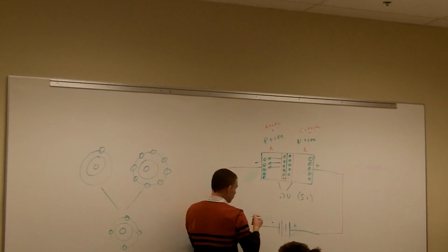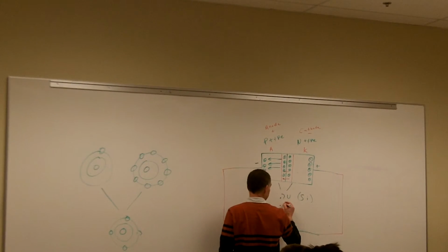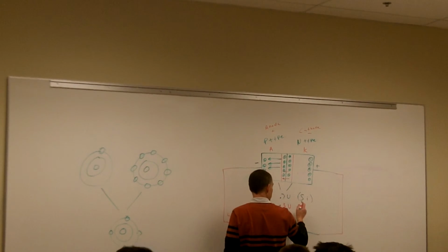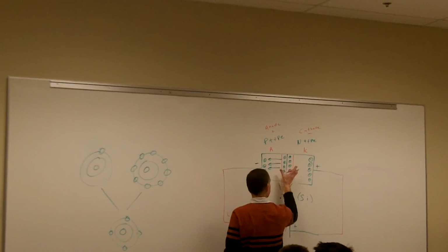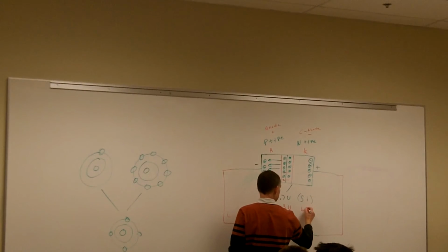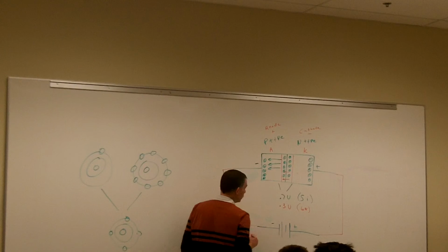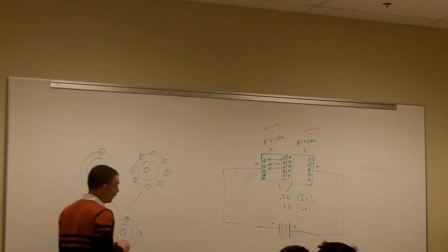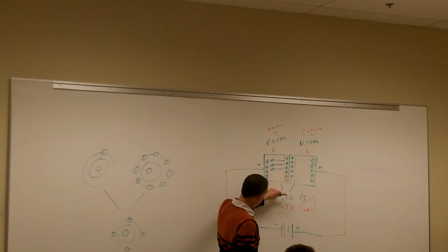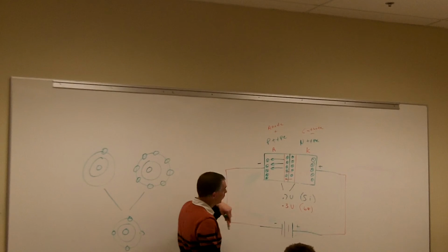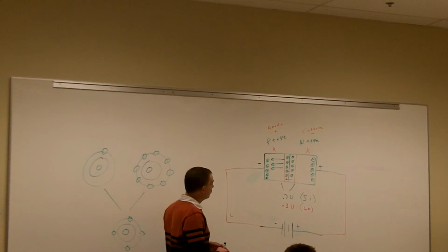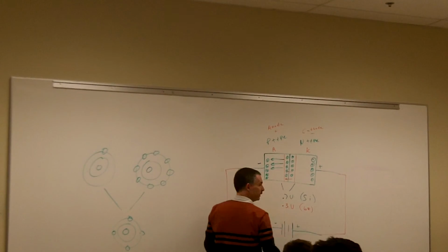On a germanium one, it doesn't take as much energy to get those electrons to flow past that voltage barrier, that barrier potential, and that's only going to take 0.3 volts. So if I measure a voltage drop across the diode and I'm only measuring 0.3 volts, it's because I got a germanium type diode in there. If I measure 0.7 volts across the diode while it's in forward bias, then it's silicon.